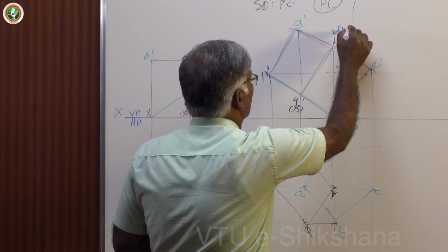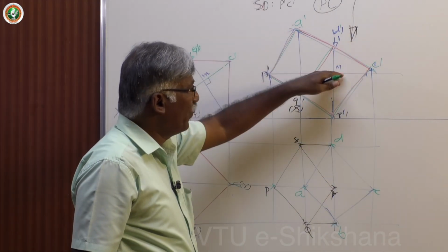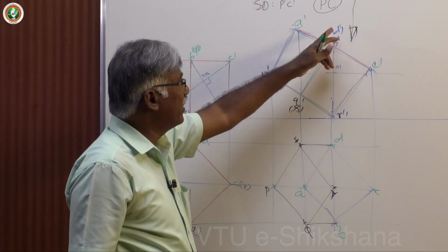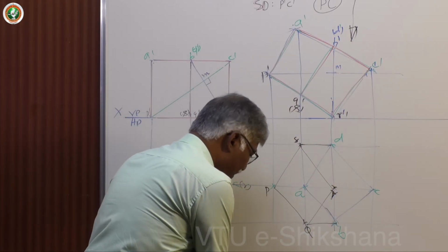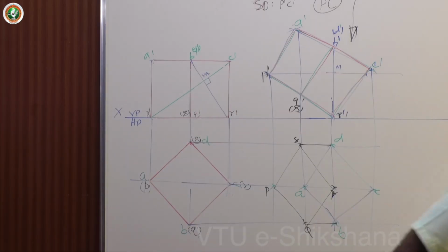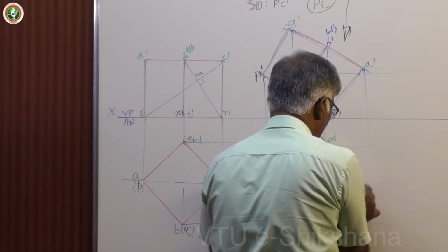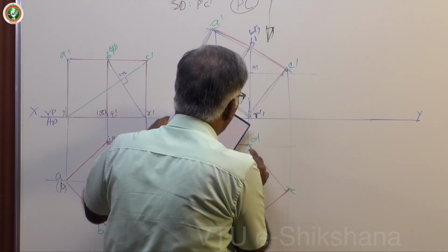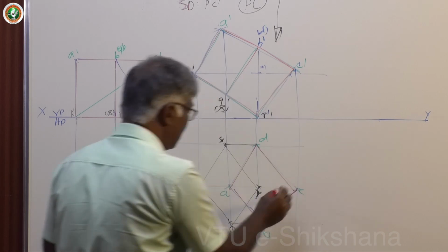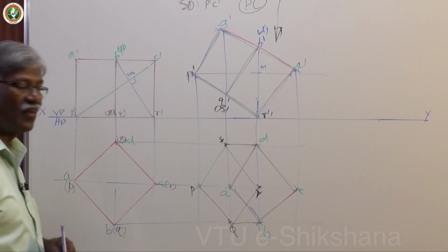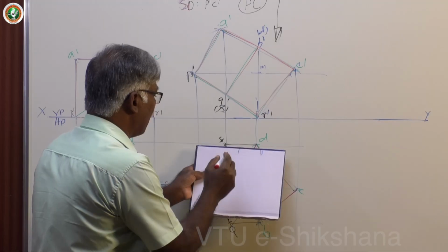Now you are here, the observer position. The top face ABCD is nearer to the observer, so top face ABCD is visible. Okay. So join all lines with dark lines. So ABCD visible edges and this is visible. Dark lines. Next, border lines completely dark.